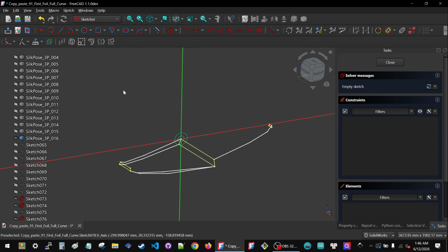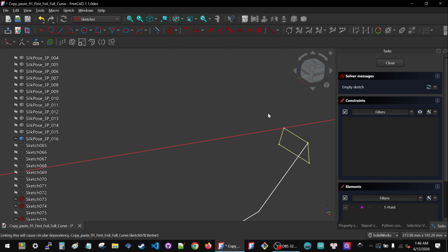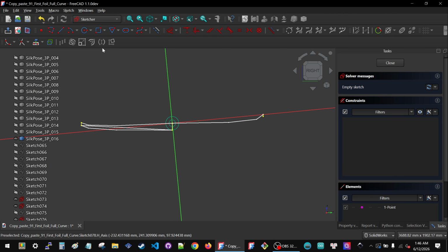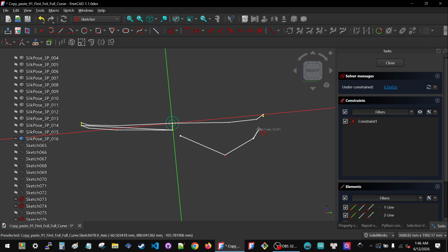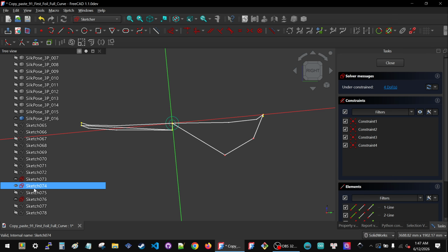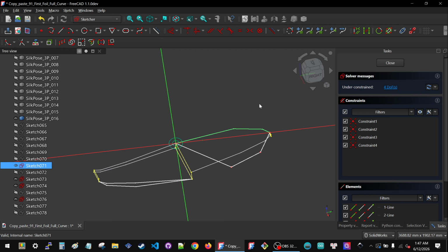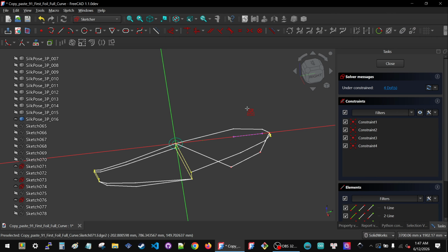Sketch XY. Import this point. Vague three lines. Snap the beginning to the origin. Snap the end to the point we already imported. Turn on 7. No, don't turn on 75. What was it? 71? Yeah, it was 71. Turn on 71. Import this line. Hide 71 again.